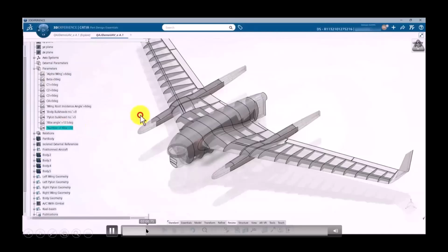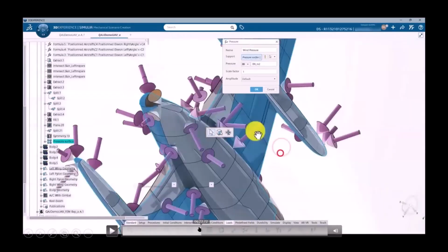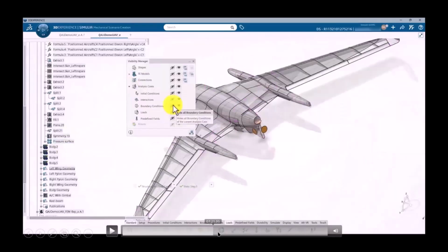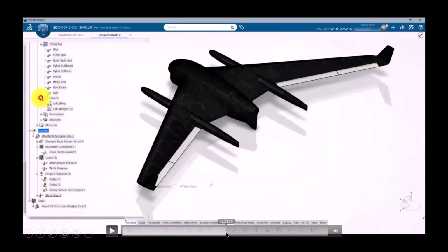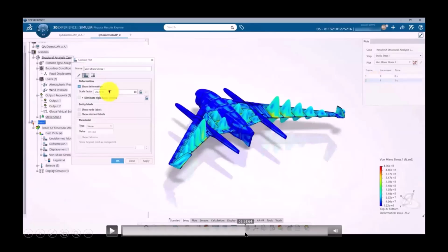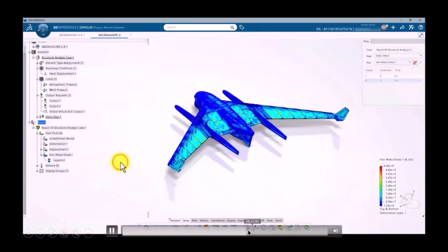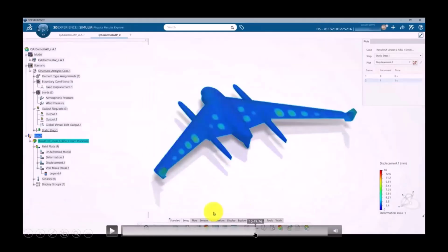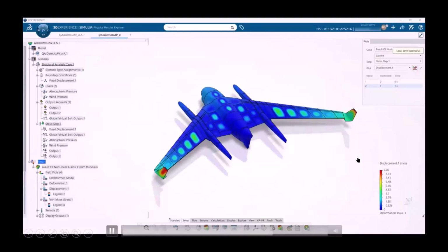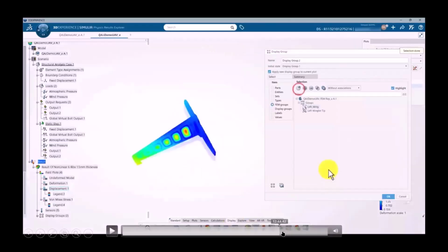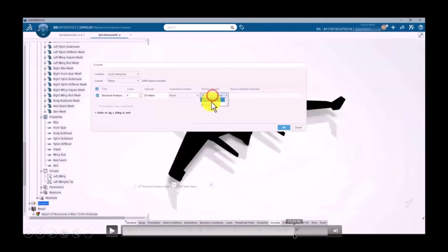So this is also quite an interesting example, and you can see all the constraints, pressure loads, meshing. Meshing is usually a difficult subject, but here on the platform it's very easy. And here you can see that von Mises stress is calculated, then deflection is calculated as well, scaling is changed. So you do several iterations and now calculate displacements and try to minimize this value below 9 millimeters, which is currently because the requirement is 5. So you're just making changes to your geometry, and you do it again and again and again.